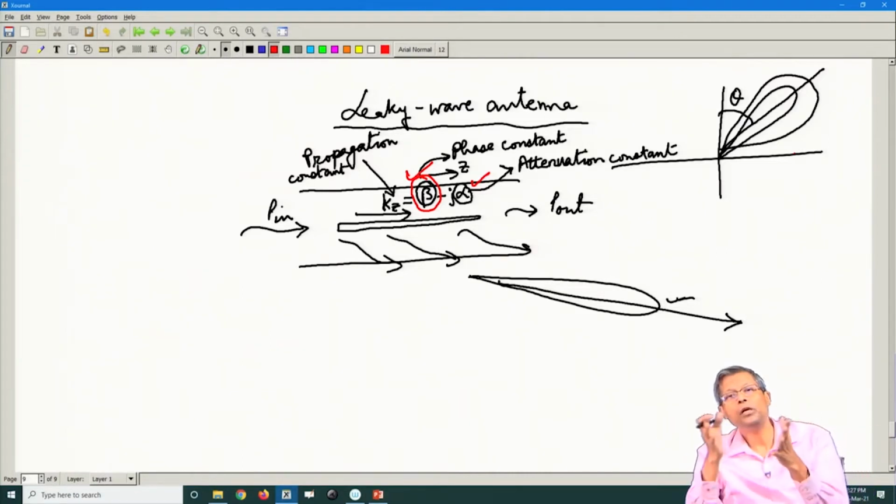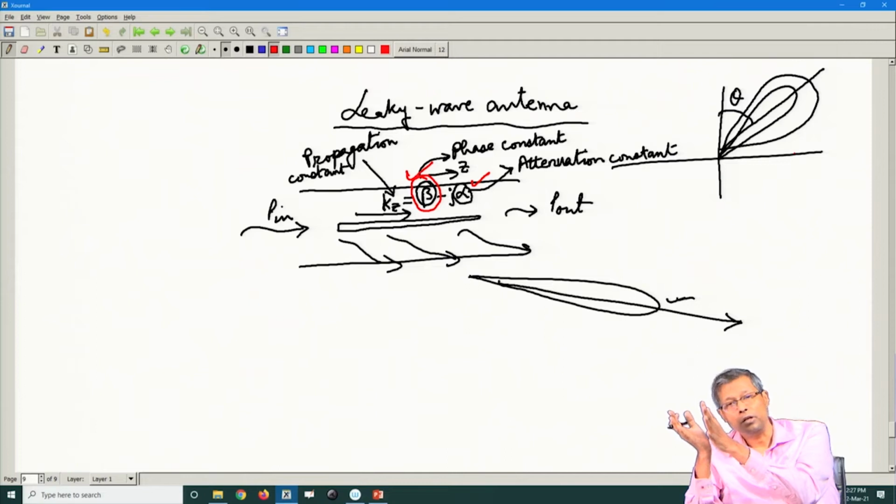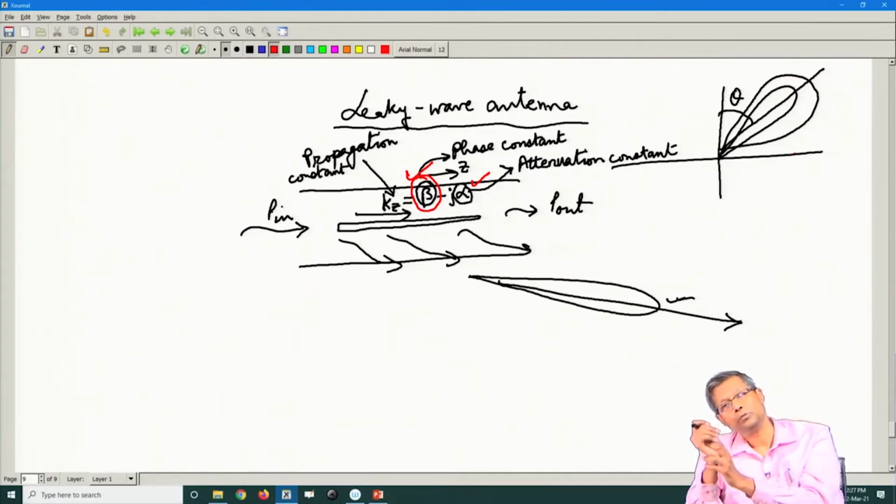So, I want to basically see the coupling problem to the antenna, the reduction of the resonant frequency to the antenna. Okay. So, these two are distinct aspects of miniaturization, because when you miniaturize an antenna, when you reduce its resonance frequency, its coupling will degrade.